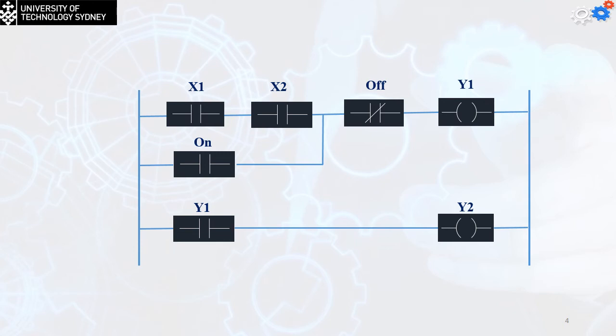For the equations, too many students ask me about the equations we are going to have supplied. Now, PLC doesn't have equations. For the G code, you are going to have all the codes. Just remember, you always have to keep the offset from the cutting edges. You always have to be on the tool path, which is offset from the edges of the cut.